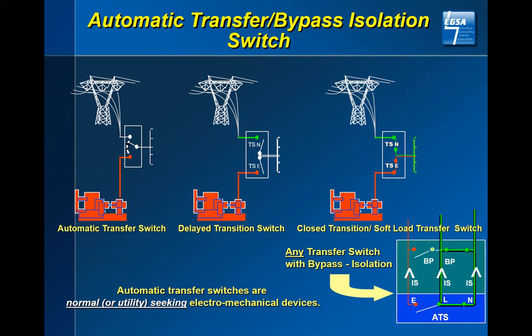And then within a ramp period of time, you will move the load from the utility to the generator at a pace instead of one load being dropped. When you're ready to go back, you will reclose. You will then unload the generator on a ramp speed, and you will put that load back onto the utility.